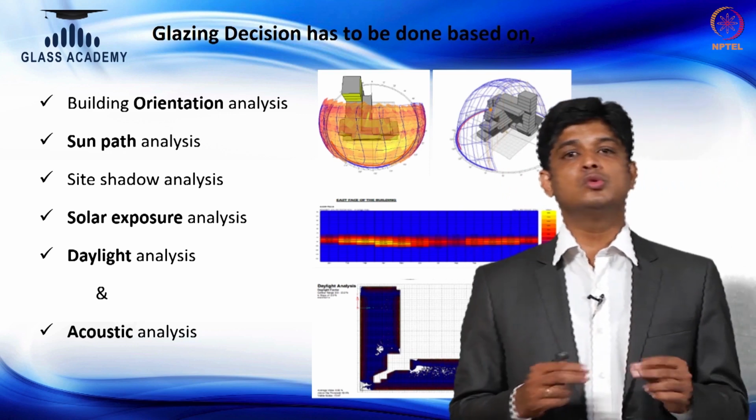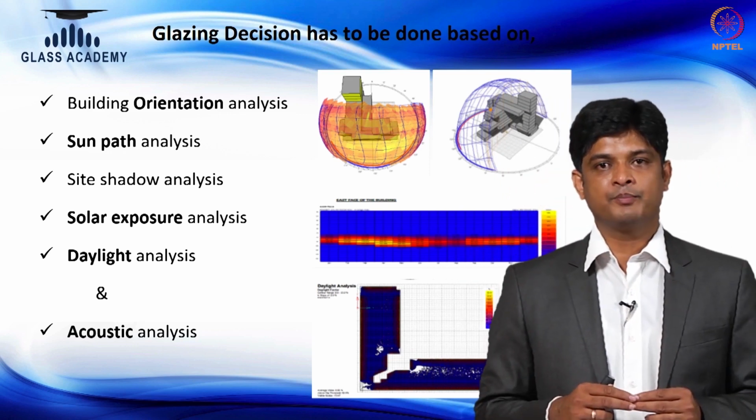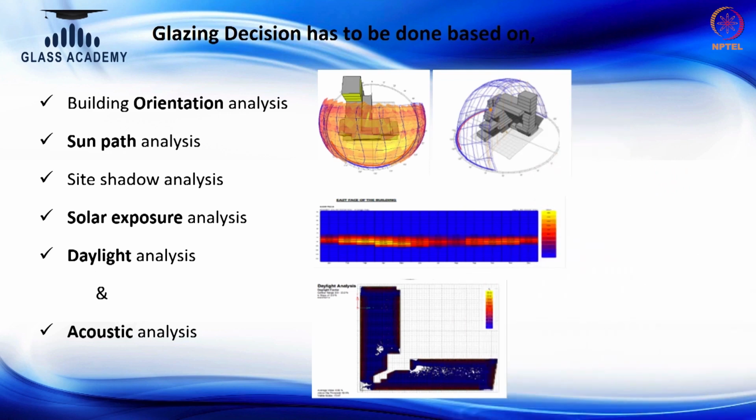The details about how these tools can be used, we will be covering in another section, which is called design tools. Even in this solar and daylight area, you have tools which help you understand the heat transfer ratios, and you have a daylighting tool which helps you calculate the lux level on your entire floor plate or at our working table height, the tabletops. Both will help you understand the bandwidth of products that you have to select for satisfying both the light demand and the energy demand, which again both have to comply with your energy efficiency code, or as per the National Building Code.